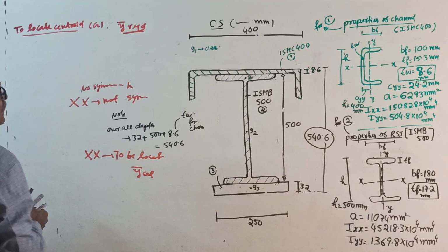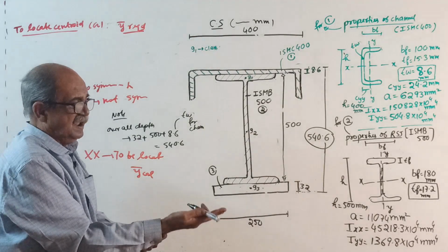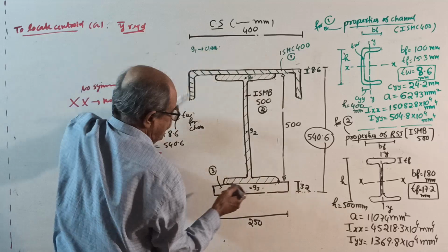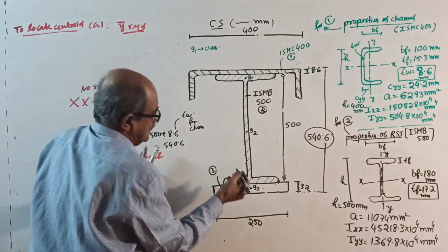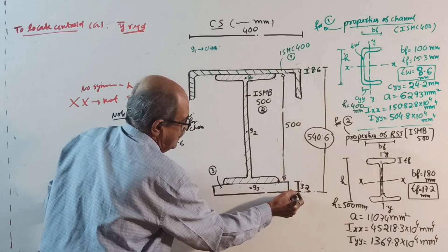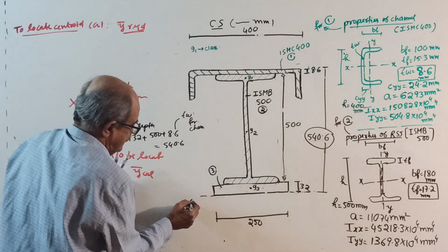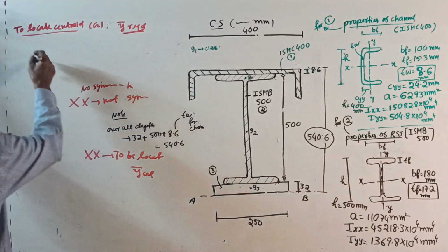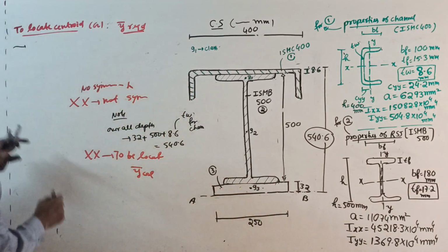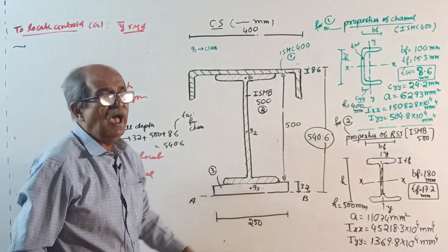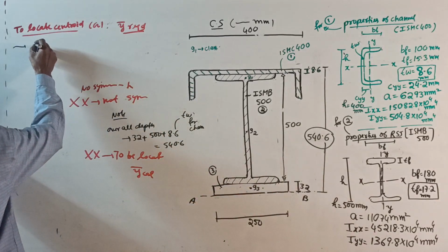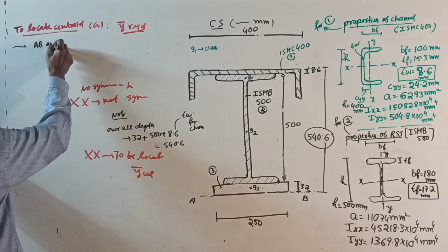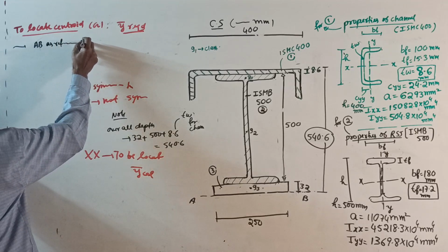Start. Take a reference line. Y bar means vertical distance. Take from a reference at the bottom side. See here, you use black color today. Green is specially meant here. Black color. Okay, this is the baseline AB. You take AB. Right here, you write: consider the bottommost edge AB as the reference axis for finding y bar.